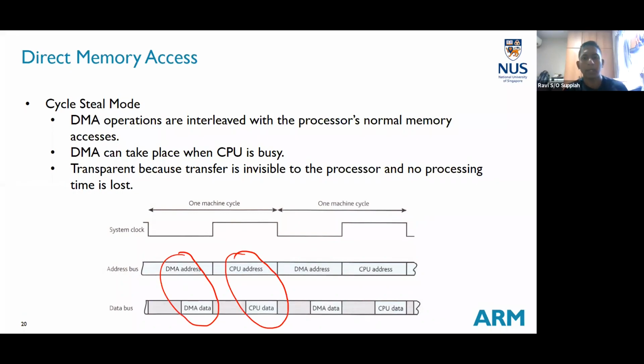If I want to use the DMA, I activate the DMA based on the registers involved. So the DMA is just like your serial port or your I2C or anything else. If I want to use the peripheral, I need to go and configure all the registers, say what I need to do, how much memory I need to move, what is the starting address, what is the ending address, put in all this information and start the process. Once it is done, I'll be able to get some interrupt or some response to say that the DMA move is complete, and then I can go on.